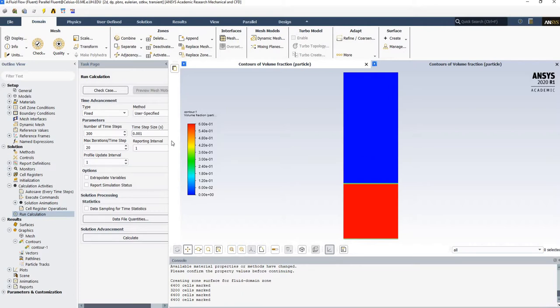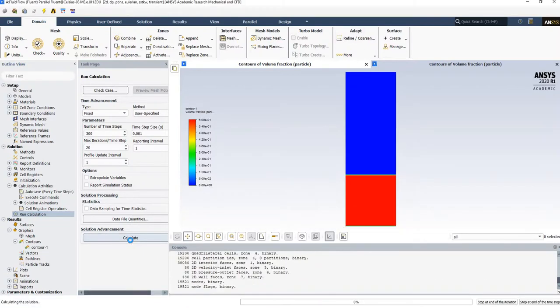And other than that, the mesh element is, so the larger your mesh element is, your Courant number would be lower. Okay, but the problem with that is if your element is very large, you lose the calculation influence, like how your accuracy will go really, really down. Okay, so these are all like double-edged swords. So you need to find a balance in between all of them that actually will give you an accurate but faster solution. Okay, so let's do calculate and see.